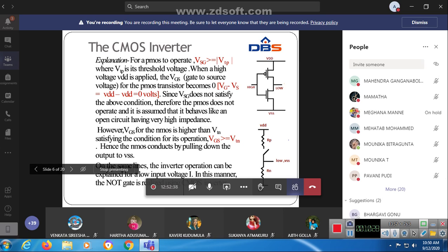So whenever we give a high input signal, the high signal will be given to both the PMOS transistor and the NMOS transistor. Wherever the bubble is present, the high signal will be converted to a 0. So the PMOS sees a 0, and for the high signal the NMOS transistor will be in the on condition.